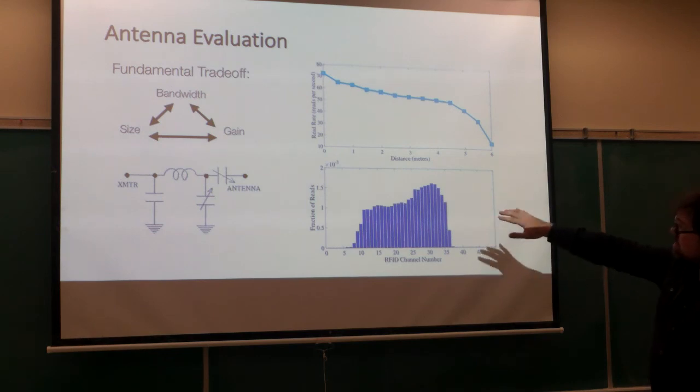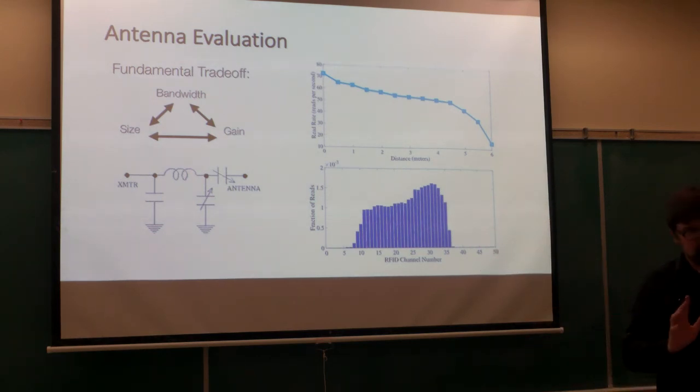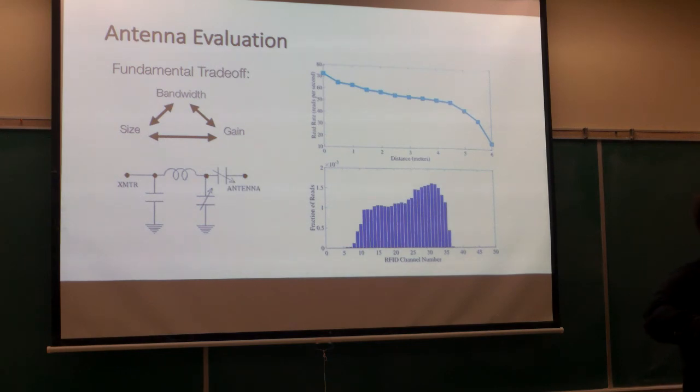So we did some engineering tricks that basically traded off throughput for range, where we ignore some of the RFID channels. RFID also does frequency hopping, like I mentioned with Bluetooth earlier. Basically, if we are hopping amongst one of the untuned channels, we just end up discarding the reading. But overall, that lets us get the 50 reads per second, but over a larger space than if we use a traditional tuning mechanism for the antenna.